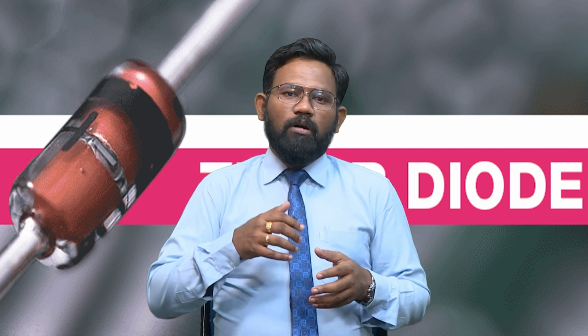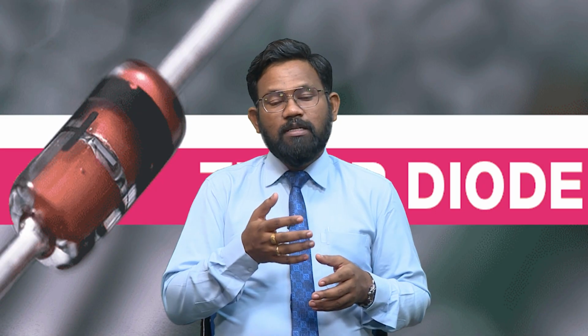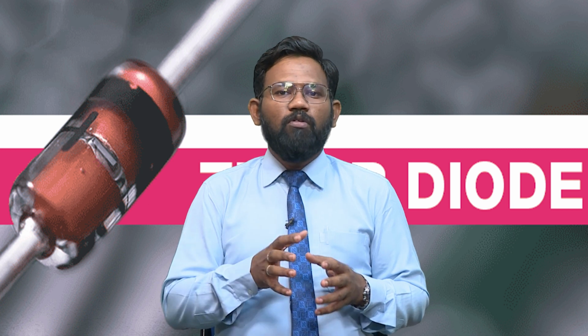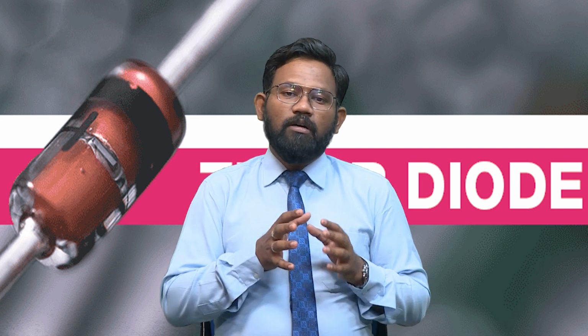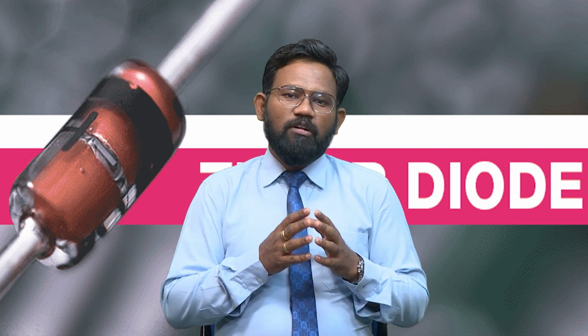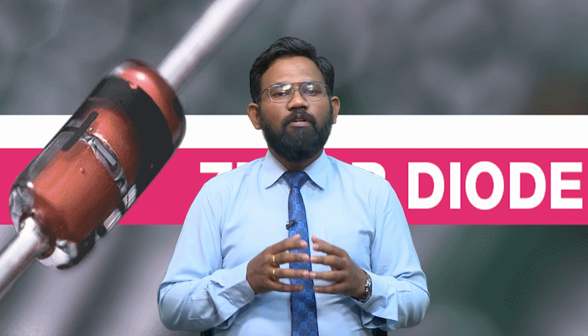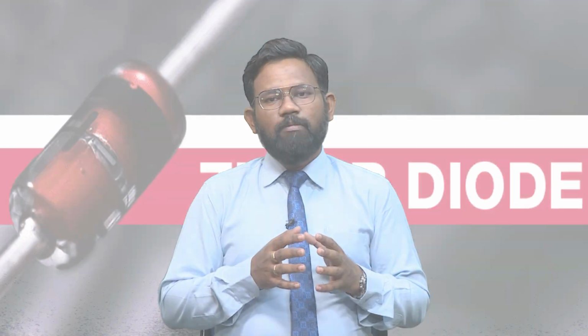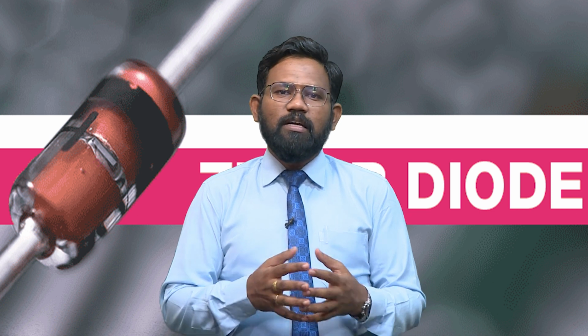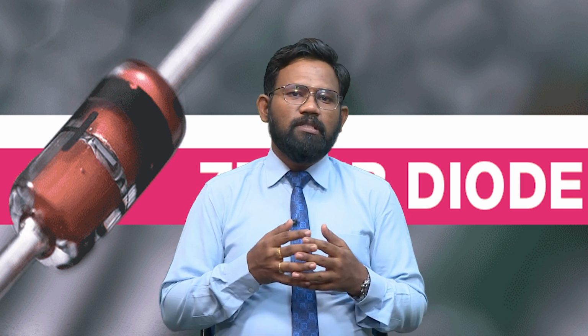So the more the doping is done, or if the diode is heavily doped, the depletion region will be thin and the breakdown voltage will be less, and if the doping is less, the thickness of the depletion region will be more, and the breakdown voltage will be more, and so on. Let us study the specifications of a Zener diode.